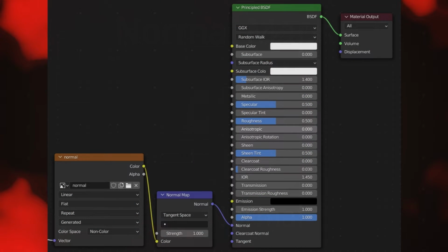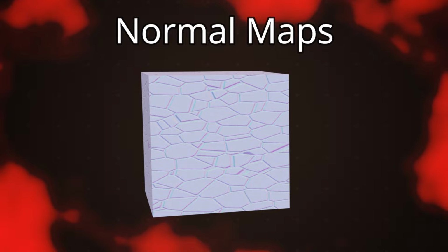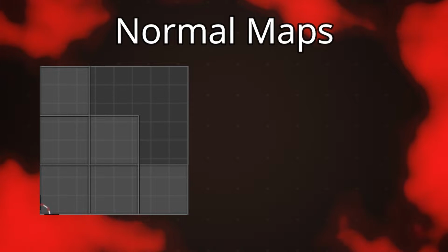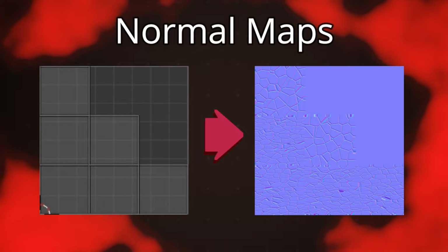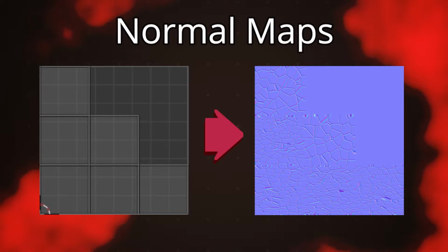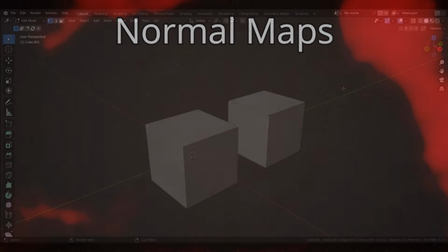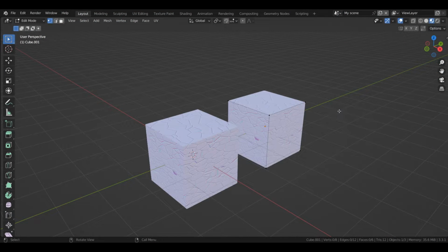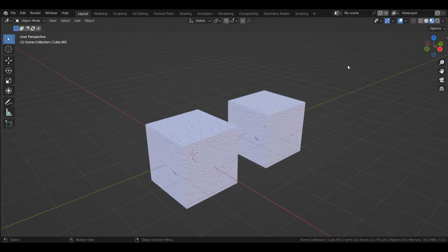When we apply this normal map to the cube, it will alter the shape of the normal at a small pixel level. So each face for this unwrap will alter its respective face on the geometry by rotating and moving the normal around at a pixel level. This creates the illusion of more geometry, but it's actually just one face with its normal altered at a pixel level. So each pixel will have a vector with a RGB/XYZ. This vector acts like coordinates to determine each pixel's orientation.